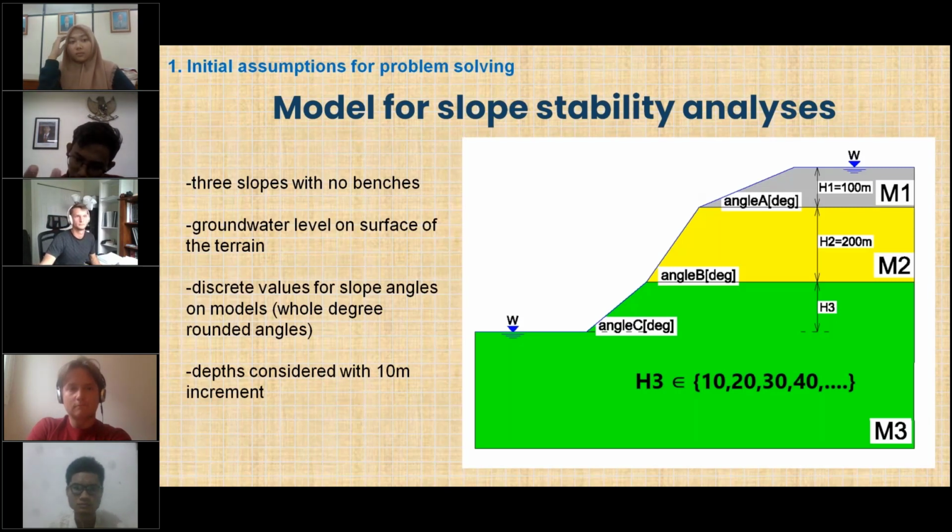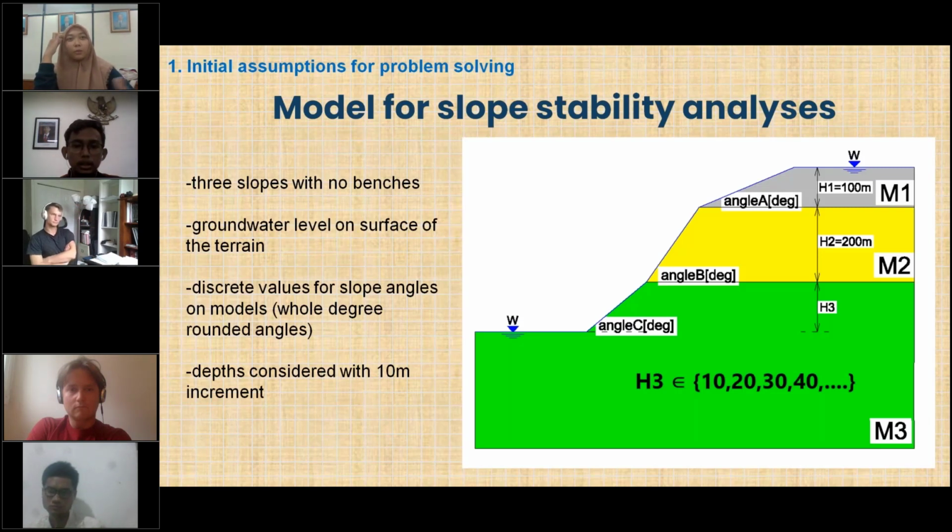Therefore, as well as for the reason that the max depth in the solution needs to be determined with 10 meters precision, the final solution was not exactly zero, but we searched for a solution that best meets the design conditions of the problem with the non-negative profit. Certainly, equalizing the profit of the final solution with zero is possible by slight modification of the geometry of the adapted model with positive profit. It could be done by a small increase of the amount of excavation, maintaining the stability of the model.